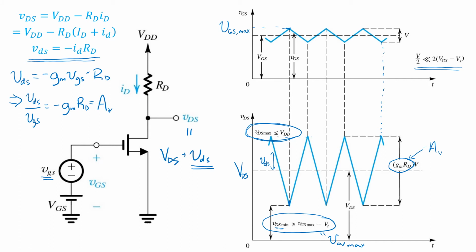If it does, the transistor enters triode, and all the assumptions upon which this linearized analysis is based, specifically our assumption about Gm here, will be invalidated, and so the predictions we make based on that assumption will not be valid. In reality, what would happen is that the waveform would start to distort at this point in time. We wouldn't see a nice triangular waveform. Essentially the voltage is reluctant to go as far below that.